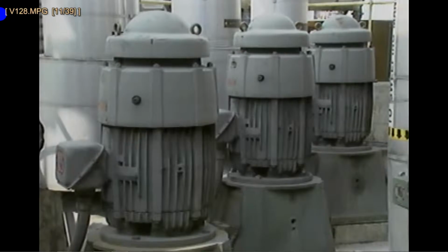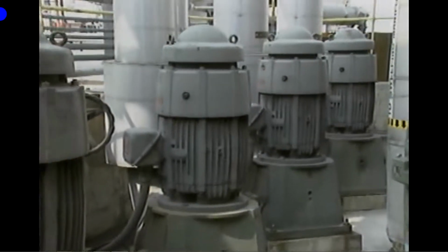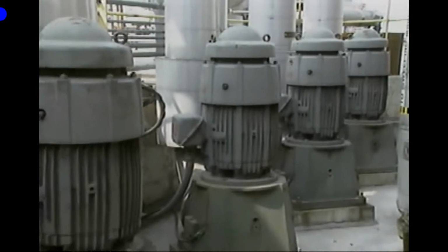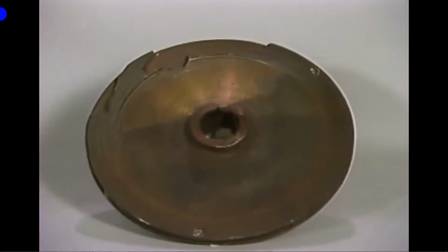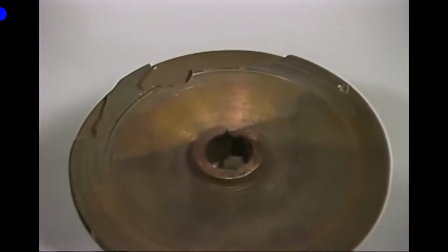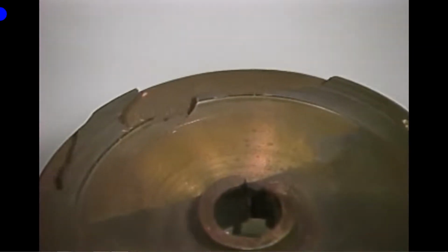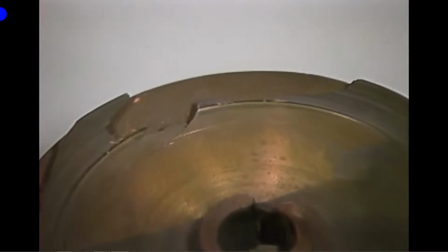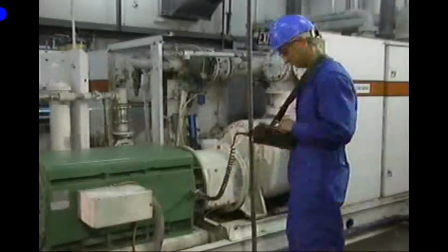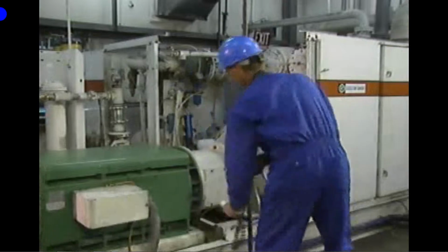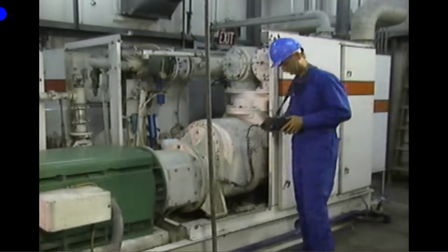Besides the effects of operating equipment at critical speeds, excessive vibration in rotating equipment is generally caused by problems with rotating components. When a component doesn't rotate properly because of damage or some other problem, abnormal forces are generated, and they occur repeatedly. These forces cause the component to vibrate. When this vibration is analyzed with vibration monitoring equipment, its cause can usually be identified.